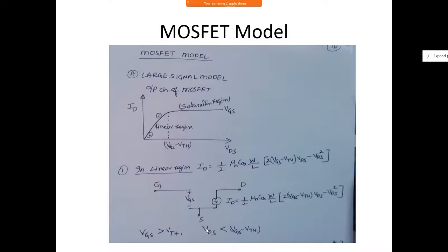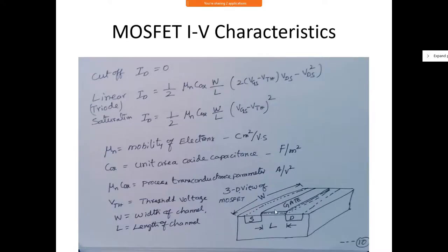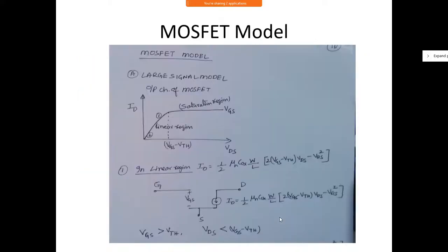I think last class we discussed, if you see the structure of your MOSFET, this is your gate. You can see there is an oxide here and there is a semiconductor. Why are we representing this as an open circuit here? Anybody? No current flows since it's an insulator. Yes, from gate, since the oxide is an insulator, no current flows from gate to source. That's what, there is no gate current flowing, so there is no current going into the MOSFET through the gate. That's why we say this is open circuited, because oxide is an insulator, it doesn't allow current to flow.